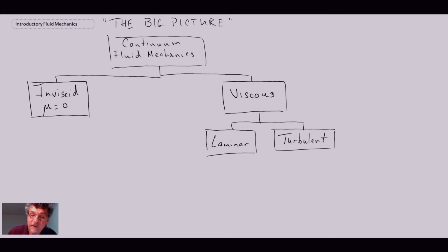But consequently, viscous flow can be laminar or turbulent for the same boundary conditions. So it's non-unique in a way. You can have two solutions to the Navier-Stokes equations. And then under that, as we go down, this is where basically our inviscid flow and viscous kind of come together. And so they can merge up again under here. And down under here, we can then have further subsets.